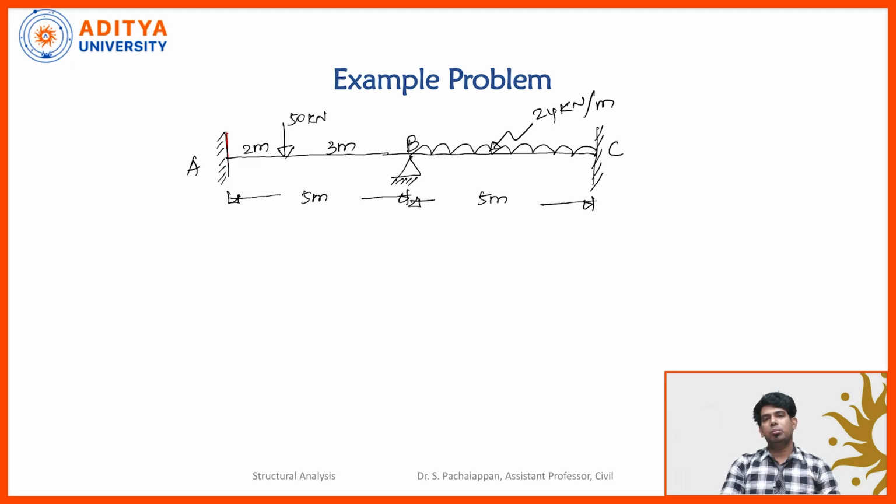I can say this beam is very simple to solve. One might ask, sir, it is a continuous beam with 2 spans, the first span has an eccentric load and the second span has a UDL, how is this problem very simple? The reason is that support A and support C are both fixed supports. In a fixed support, the slope is 0. So, very easily in the slope deflection equation, wherever theta A comes, I put 0, and wherever theta C comes, I put 0. That is why I told you this problem is very, very simple. We will go step by step to solve this problem.